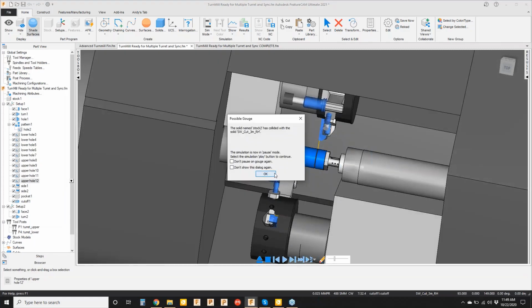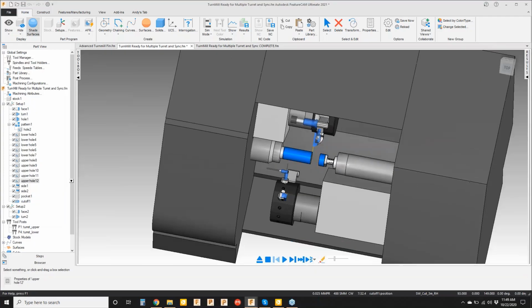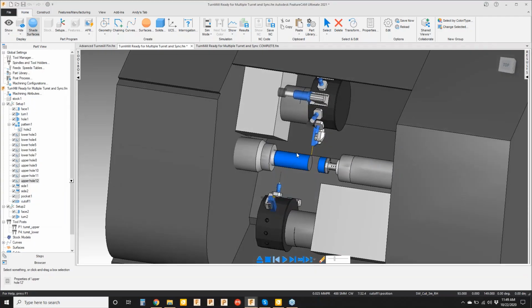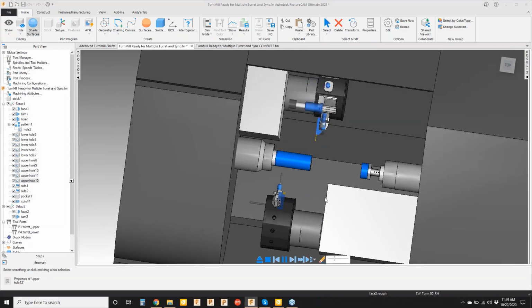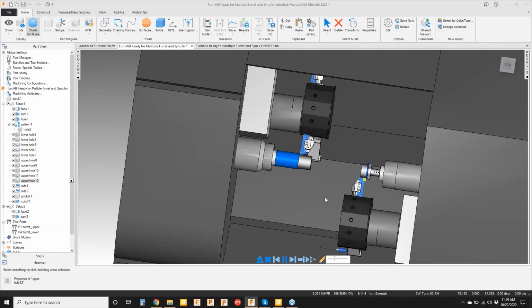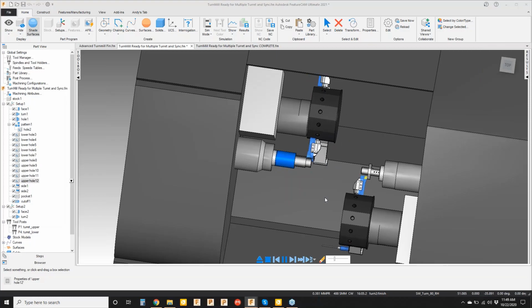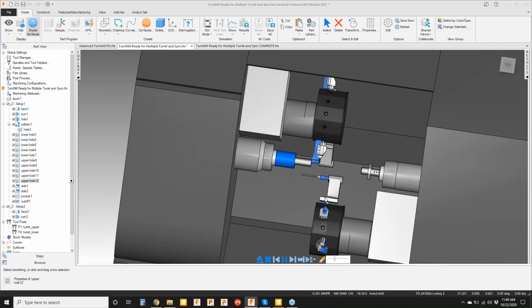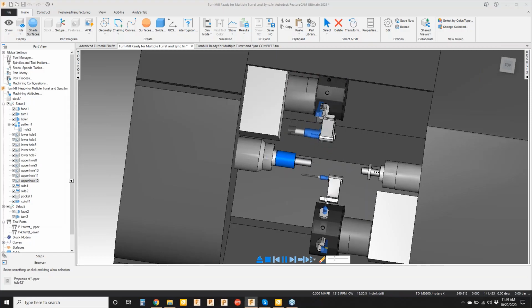You know, typically what I've noticed is on a retract, it's a rapid move, and so FeatureCAM thinks that's a collision, which you may be okay with, no big deal. You could have that modified in your cutoff process to be a feed move out and not have that. And so now we're seeing the completed work happening on both sides, and we'll take a look at the NC code in a minute, and then I'll show you the actual time we saved to show you this really complex part and how CAM software definitely benefits you.